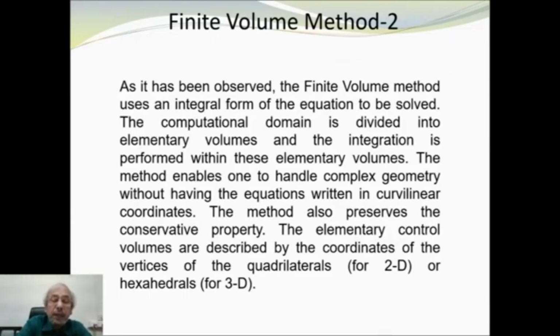The finite volume method, if you recall, we mentioned that the finite volume method uses an integral form of the equation to be solved. The computational domain is divided into elementary control volumes, and the integration is performed within these elementary volumes. The method enables one to handle complex geometry without having the equations written in curvilinear coordinates. The method also preserves the conservative property.